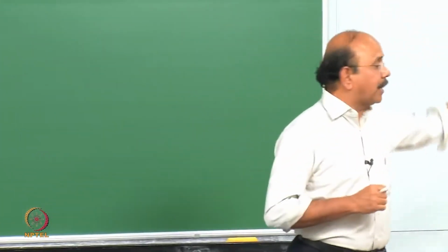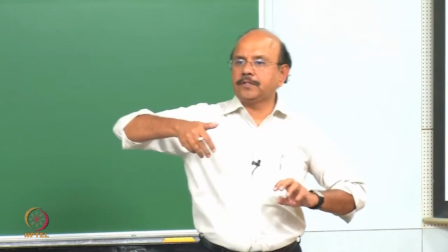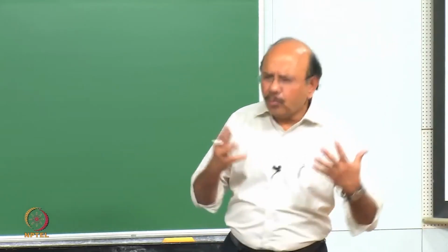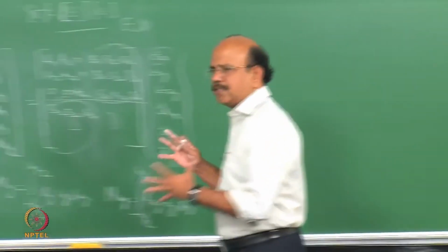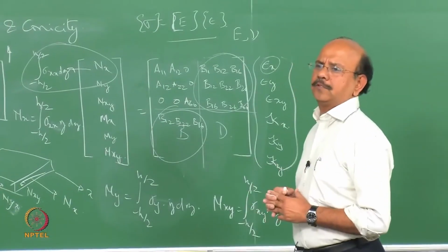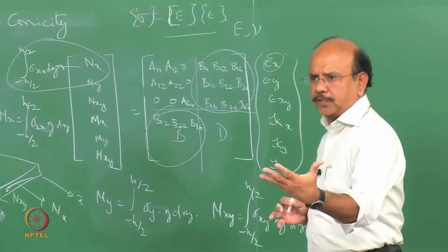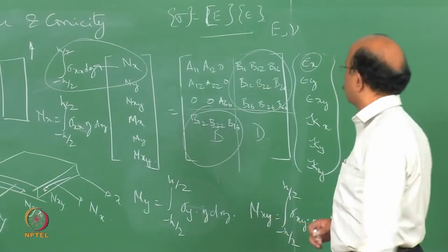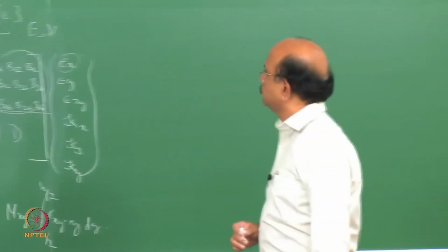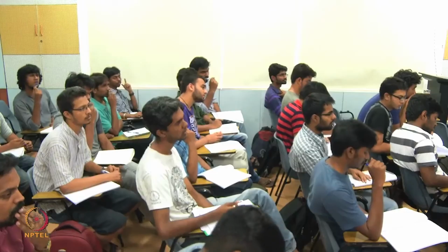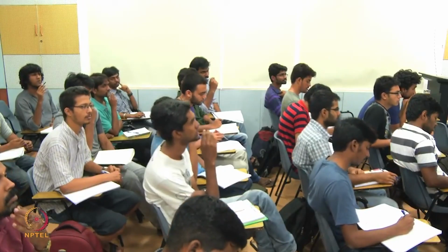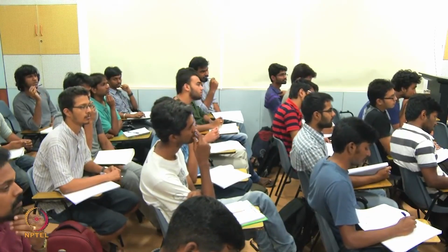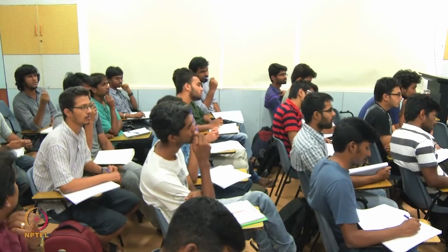So that's what happened here: when I stretched, twisted, and so on. How do I apply this? What are we talking about? Why are we talking about this? Changing curvature gives rise to a force. Fine. So why am I worried about it? Because even though the tire moves in one direction, the deformation in one direction means there will be a reaction in all three directions as well.